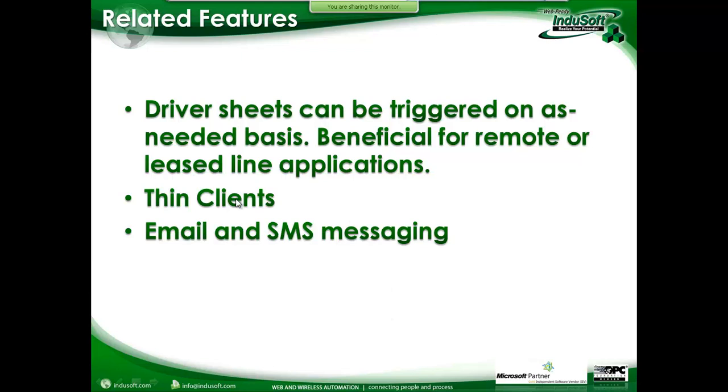Thin clients: InduSoft Web Studio supports 3 different types of thin client applications where you can view on up to 128 remote stations, whether it be Internet Explorer or using our secure viewer software to view and interact with the screens remotely, or our third type of thin client, which is called Studio Mobile Access, or now just Mobile Access, whereas now on any HTML5 compatible browser you can use InduSoft Web Studio or the thin client to see back to InduSoft Web Studio and interact with the tag values, process values, alarms, and trends.